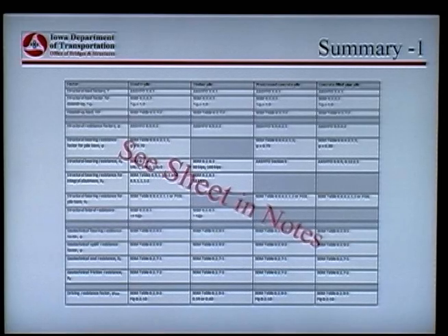And then this is the screen version of that last sheet that you have. What I've tried to do there is go down the first column and list the various factors. About the top 60% of the table or thereabouts are structural, then geotechnical, and the driving resistance for each of the different pile types.